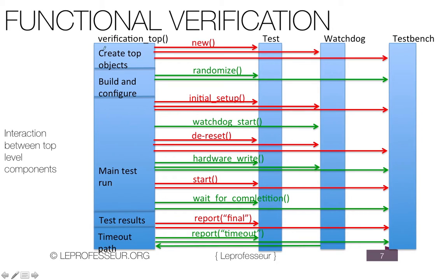Here you have the object factory which is creating different kinds of objects. Think about brick, right? So it's a factory of bricks. Now bricks may have different sizes, different kinds of bricks. So you are generating different kinds of objects, and then you are configuring those objects to have different properties, maybe blue color brick, red color brick. Basically I'm trying to say that you are randomizing, right? So when you randomize, you improve your coverage, you exercise more and more data points in your input space.